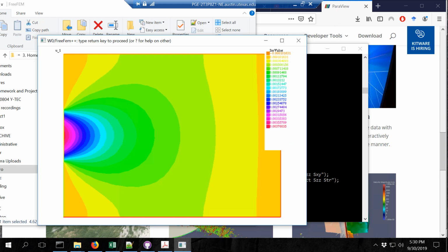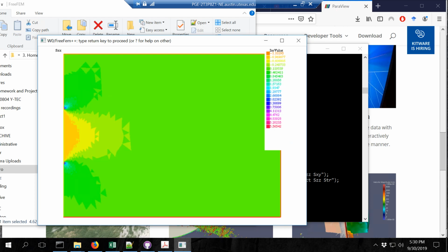It has to be very fine in the side of the fracture. And this is the stress that you get by applying a pressure. In this case, this is displacement number 1, this is stress in direction x. For this case, I added, if I remember correctly, a pressure of 1 megapascal. So if you look at the values over there, it's close to 1.